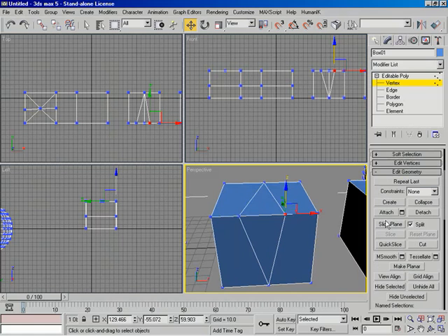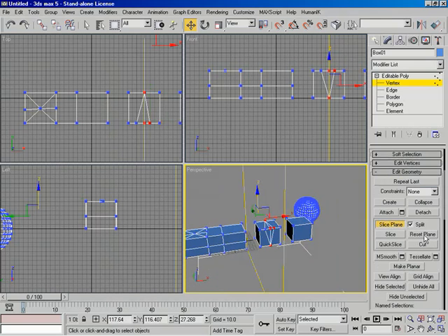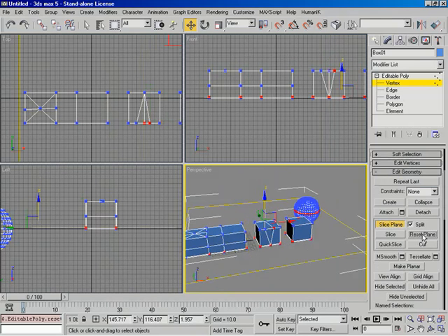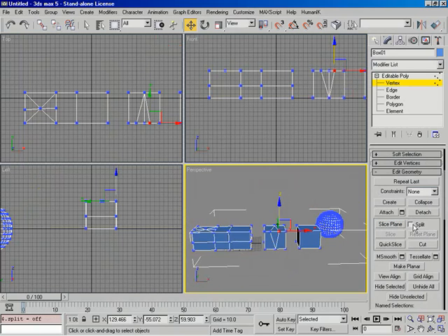So coming back down, we just took a look at the slice plane, slice and split. The reset plane over here, if I turn my slice plane back on, you'll see we're still rotated at 90 degrees. I can simply come over and click reset plane, and that'll just reset the plane back to the original size and orientation that it was originally at. Let's go ahead and uncheck split because this could bite us with quick slice, which we're about to do. So in other words, split's used with slice and quick slice.